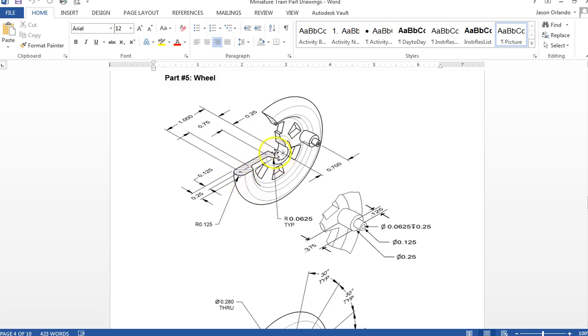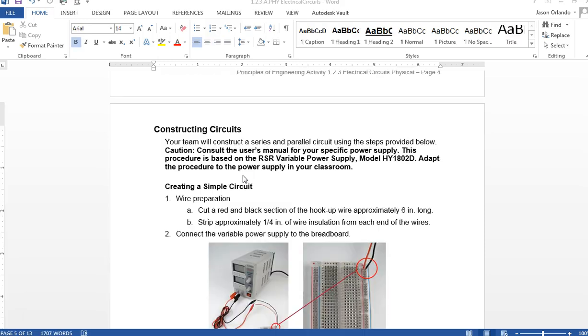Okay, so basically I'm going to make this profile right here, and I'm going to revolve it around the kind of an axis. Everything's dimensioned off of that center line, so I'm not even going to worry about making the hole until afterwards. So I'm going to basically have a kind of rectangular shape that comes out here, okay? And so we're going to have to get these details. Let's look at the dimensions right away, though. We've got a 1 inch dimension out to here, and then it's like a semicircle. So how about we try that?